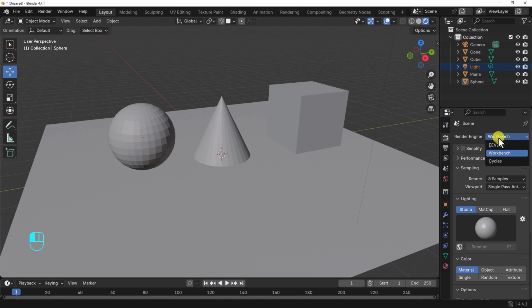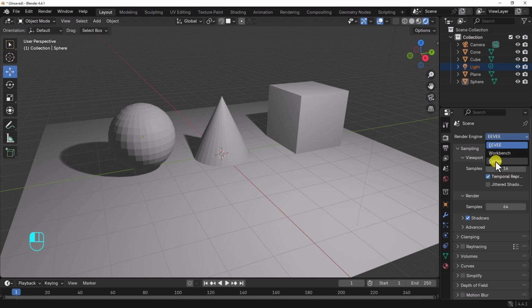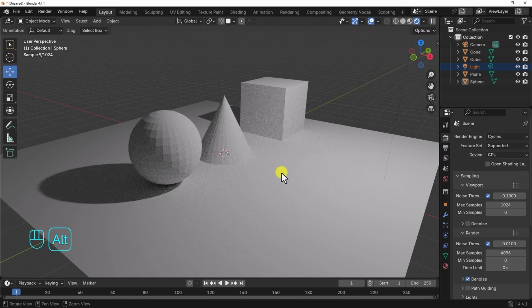This is intended primarily for quick testing of animations or modeling without being bogged down by textures, reflections, etc. Click on the Cycles render engine. You may have noticed the scene changed just a bit in quality. You can toggle back and forth between EEVEE and Cycles to see the difference with this current setup. Cycles is a path tracing renderer like ray tracing that uses a physically based renderer designed for very realistic results.